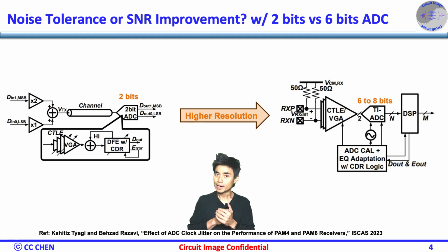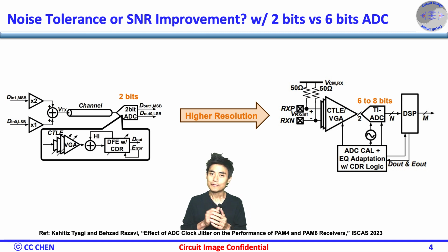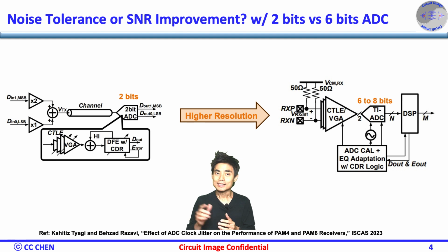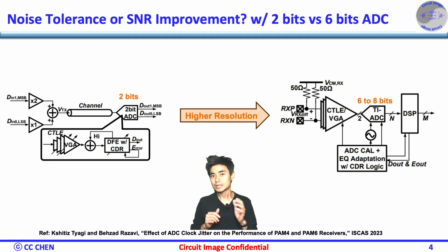Make sense? To balance the power, performance, and area, etc. trade-offs, people choose the ADC resolution range from 6 to 8 bits, which indicates a signal-to-noise ratio SNR of 38 to 50 dB ideally. If the 6-bit ADC can really convert and provide the front-end signaling information precisely in the digitized format, the DSP can improve the residual signaling imperfection by different algorithms flexibly. The DSP is to help further reduce the residual ISI, reflection, nonlinearity, surprise noise, and minimizing intrinsic thermal noise. Then the eyes can equivalently see a bigger PAM4 eye and achieve a higher input sensitivity robustly over PVT.